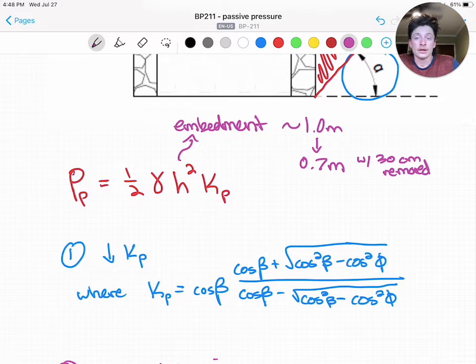If you remember from the Bridges to Prosperity manual or the P active calculation, this is simplified to calculate for flat surfaces, but you can try calculating Kp on your own and play with the beta value and see how this changes the value of Kp, the passive pressure coefficient. You can change this to -5, -10, or -30, and you can see how drastically Kp reduces.